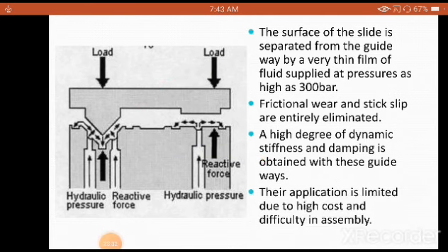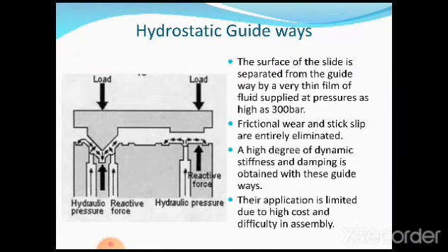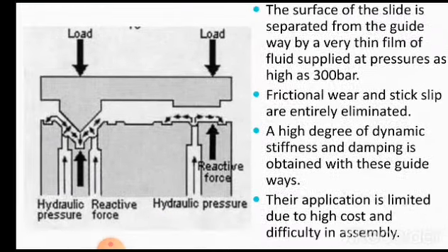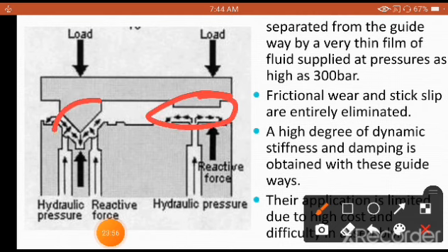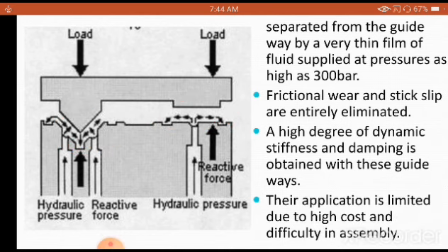So frictional wear and stick slip are entirely eliminated. There is no question of any friction here. The reason is very simple: the contact is purely due to the oil film that is being formed in between these two surfaces. The thickness of the oil film itself is used for preventing the generation of friction, and there is no question of any stick slip phenomenon as we have seen in friction guideways.